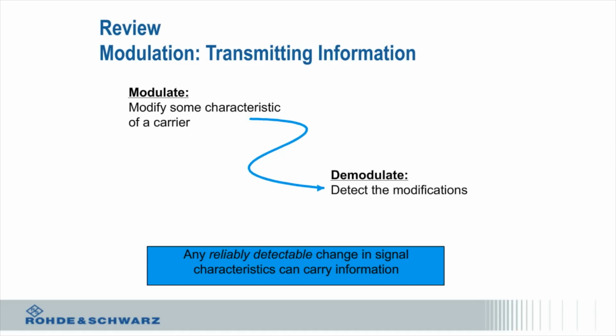But the key thing is, taking that information, you have to put it on that signal, which we call a carrier, and that carrier really is the thing that propagates through free space. In cell phone technology, that's typically around 1 gigahertz, and in wireless communications like 802.11, Wi-Fi, things are transmitted over 2.4 or 5 gigahertz.